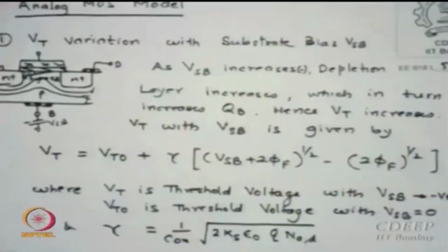Now there is some issue which may appear. We always thought the transistor behaves in a very nice, simple way, but unfortunately it does not, particularly if it is a short channel device, where it will be even worse. Even with a long channel we would now like to see what the equivalent circuit of a MOS transistor is, which I can employ in circuit designs. There are many other issues which I have not yet discussed, and one of the issues I start with is that I assumed the threshold was constant.